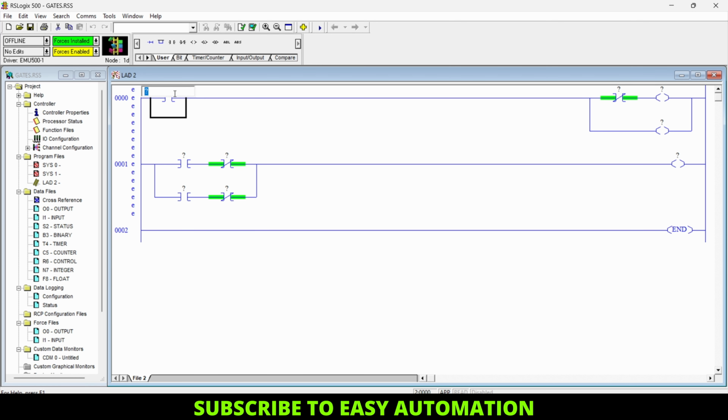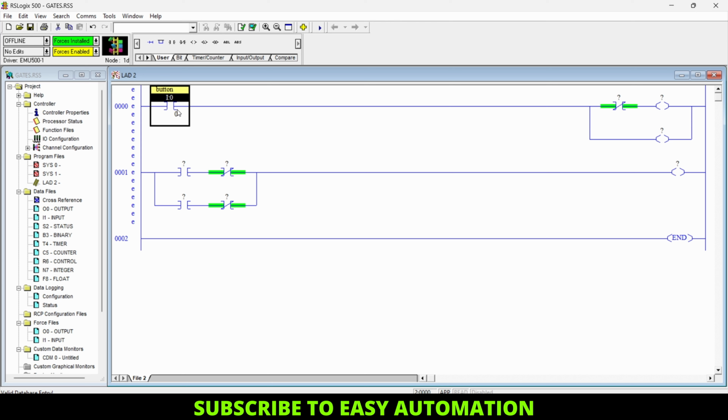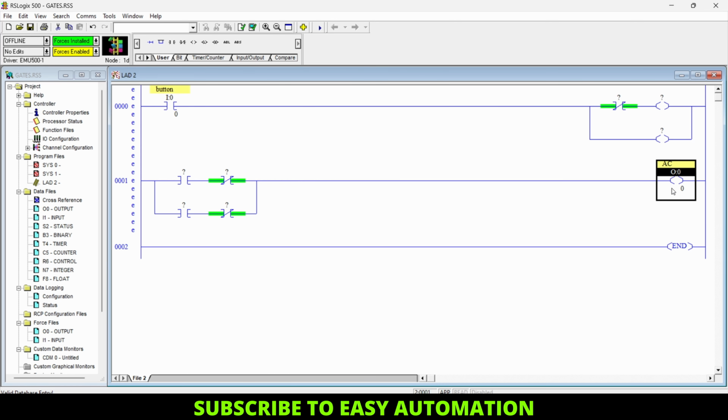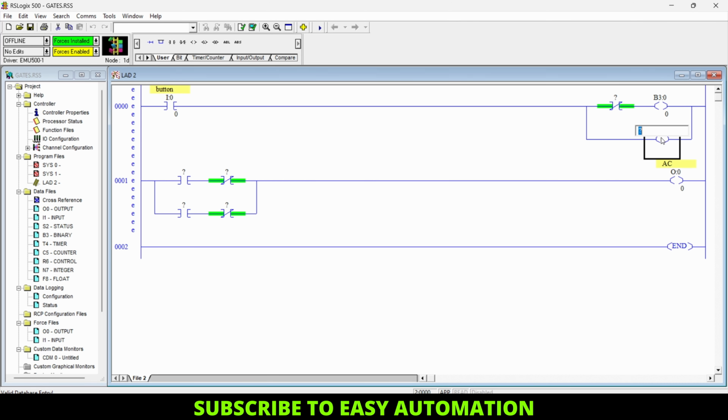So I will give the addresses. I will name this one button. This NO contact will be our button by which we are going to turn on this output. I will give the output address and name it AC. So this output will be called AC, and this will be our button. For these outputs, I will give the memory bits B3:0/0, and for the second output I will give another bit address, about which I have taught in my previous video.